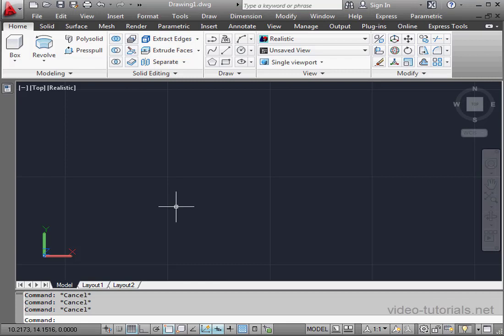Welcome to our tutorial about curvature. Curvature is an important principle for surface modeling, and it basically describes the deviation from a flat line or a flat surface. The smaller the radius, the higher the curvature. We're able to assign color to curvature values and visually evaluate the smoothness of our surfaces.